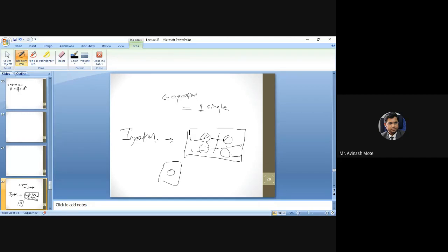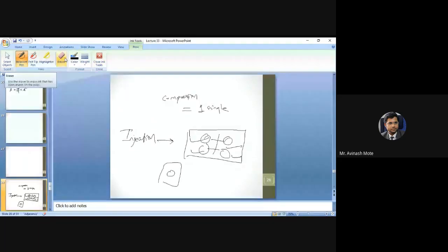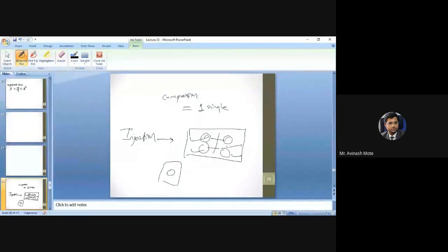Now in compression molding we calculated a projected area for a single cavity. Here we have more number of cavities, so obviously we have to go for that many times the projected area. Are you getting my intention? In injection molding, most of the times we have a multi cavity setup, so we have to go for that many times the projected area.